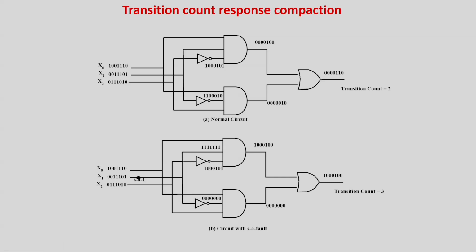So what it tells basically is that for a given circuit and a given fault, which aliasing method will work better, it depends. What I have tried to show you here are not very good kinds of aliasing techniques. As I told you, a lot of theories exist for LFSR based compaction techniques which give very low aliasing within very low area, but they are more theory intensive. So I have not covered them in this lecture, but as additional material you can read about them.